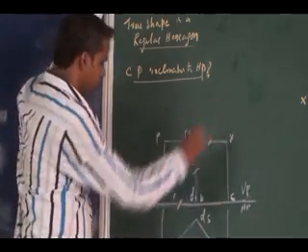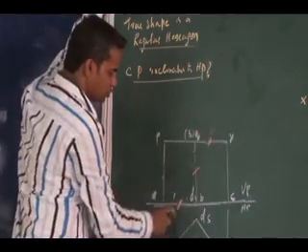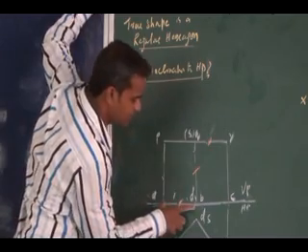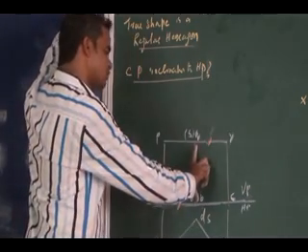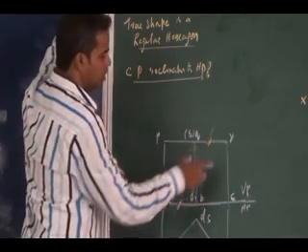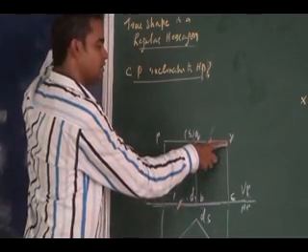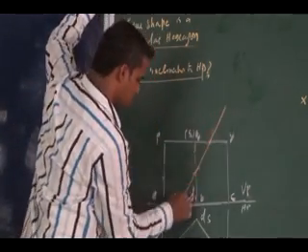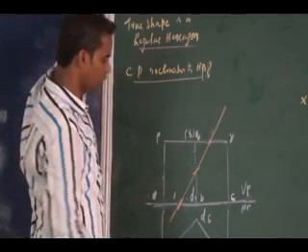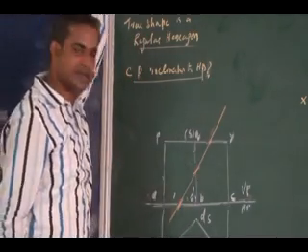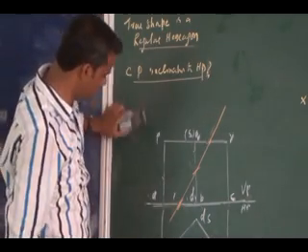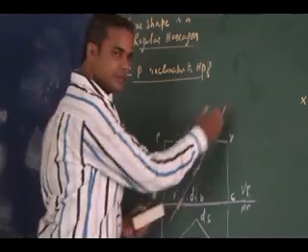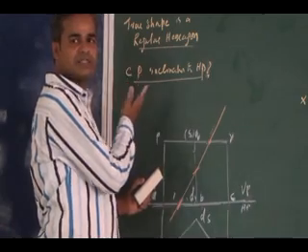Right, so the cutting plane, as I told earlier, it should cut 6 edges of the cube. So if you mark the middle of this side, the middle of this vertical edge, and the middle of this base side in your front view, then if I connect these middles with the cutting plane, it will give me a regular hexagon as a true shape. So that is the thing you should remember here. Neatly you draw the front view, top view and represent the cutting plane exactly in the middle and try to get the true shape as a regular hexagon.